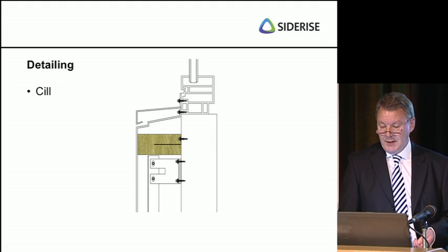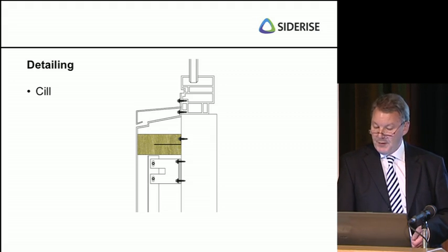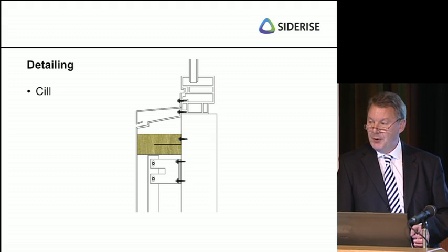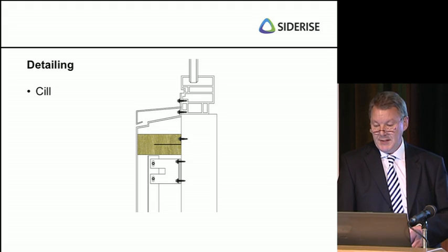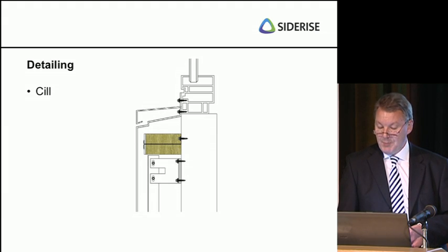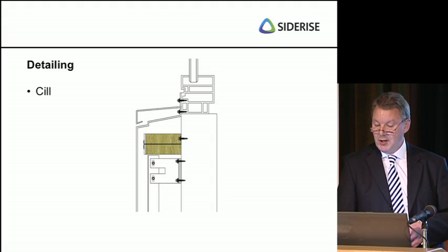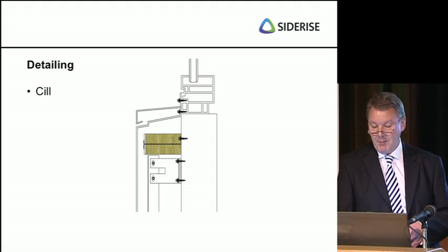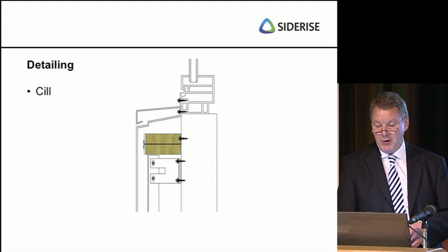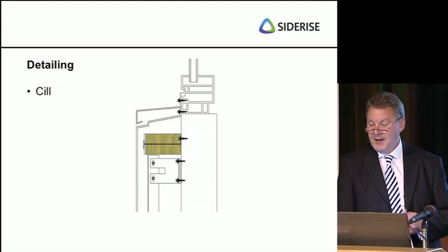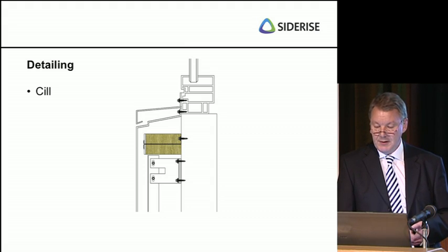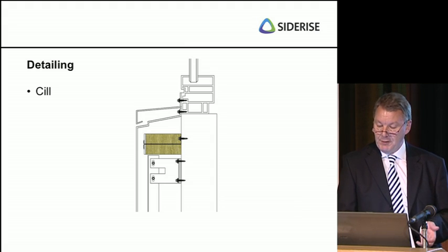At a sill detail, where the top of the cavity is sealed by a sill pressing, it's common for a horizontal full width barrier to be installed. An EPDM might be required but omitted here. Alternatively, perhaps a better solution in this location is to use again a horizontal barrier with an air gap, which is ventilated to allow for potential drainage. This may be considered a safe option in case there's a breakdown of any seals on the sill. In that event, water would have to go somewhere, and if we have a full width seal underneath, where would the water go?